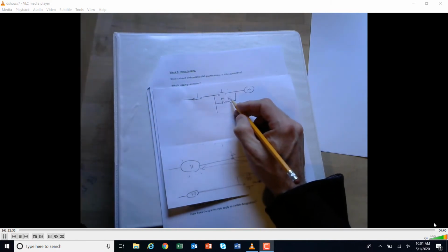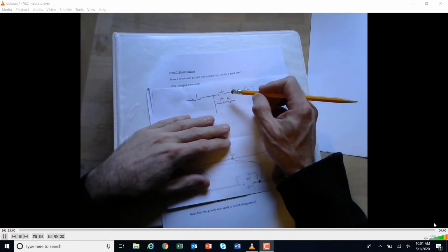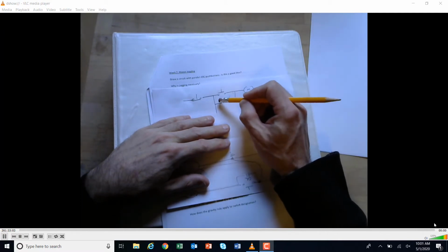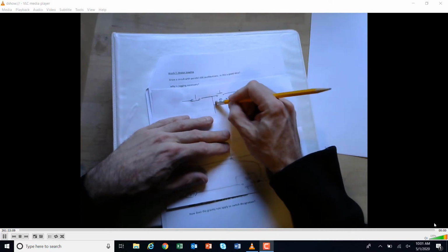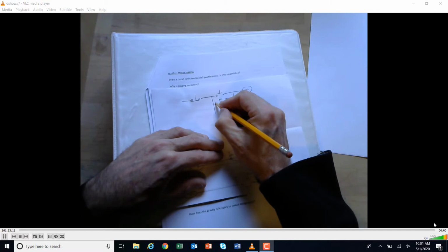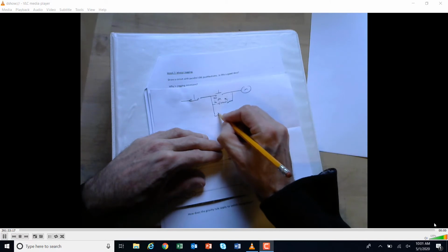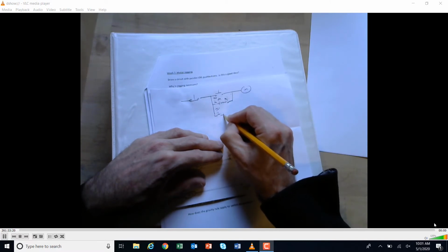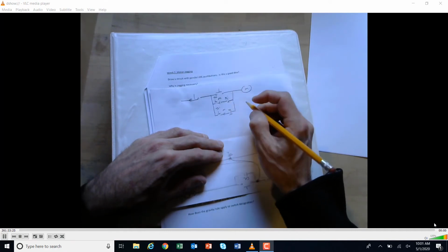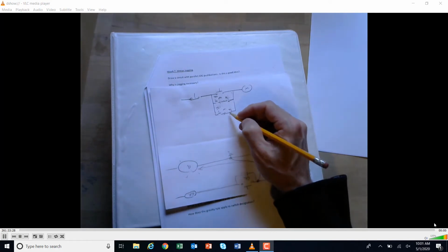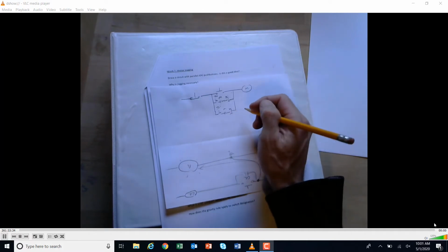So now, if you wanted to draw something with parallel jog push buttons, that would be a run. I guess you could put another push button here. Maybe you'd have to hit the selector and hit the jog button. Or down here, you could have a jog button number 2, and maybe you put some memory, and you could use the selector switch here, tied into both, okay? So maybe I hit the selector switch, and I could either jog from here or jog from here, maybe something like that. There's other ways to do this.